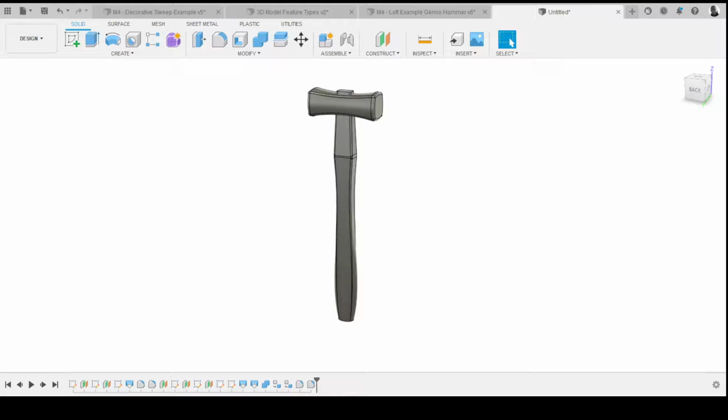Hopefully, you can see that, it's quite straightforward lofting. It's just being logical: creating your profiles step by step, making sure they're on offset planes, making them aligned if they need to be aligned, creating guide rails, making sure guide rails are connected. It is building that wireframe.